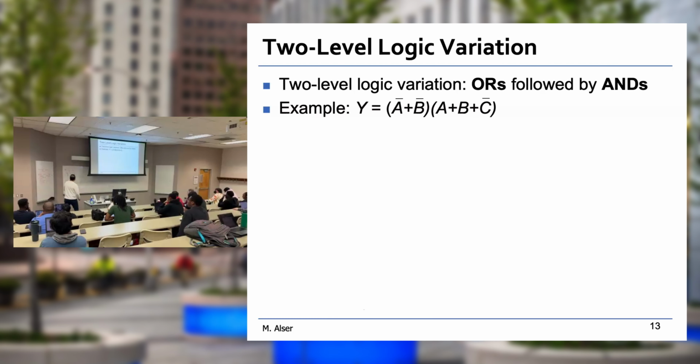Okay. Now, can we use something similar to this? Of course. Yeah, you can start drawing by that. But remember, this is not sum of products. This is product of sums. Each term has a summation inside it. There is no sum between 2 terms, right? There is a product between the terms. And that's telling us that we should have here something followed by something else. What should we have over here? OR gates. Excellent. So here should be OR gates.